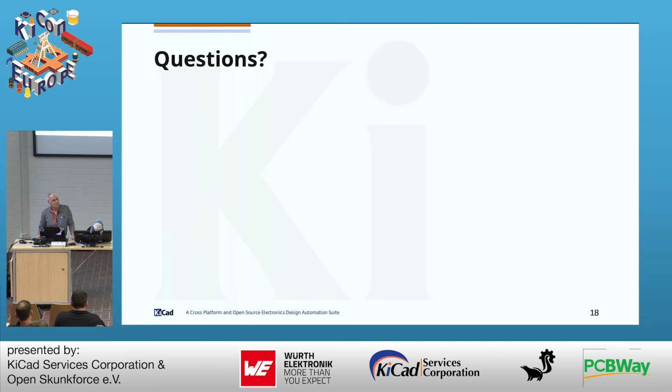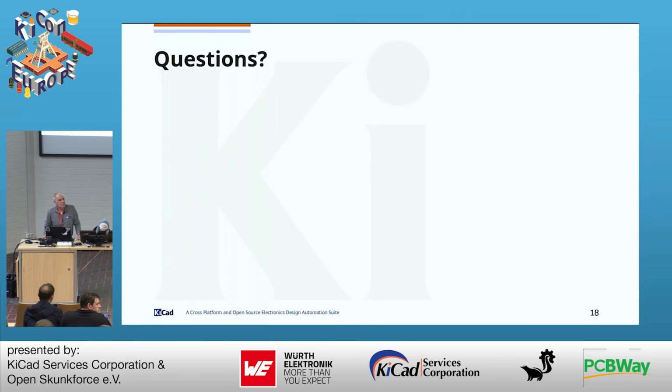Second question, I also like the notion that I have a symbol and I can have various footprints assigned to that. But I'm a little bit wondering how you'll do this in the program, because the way I did this is I just put several transistors side by side and said DNP whatever I didn't want, and it's pretty straightforward. So what happens if I delete a variant with a certain footprint? Will it go away from my PCB?